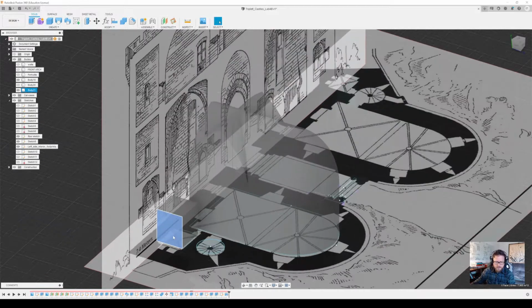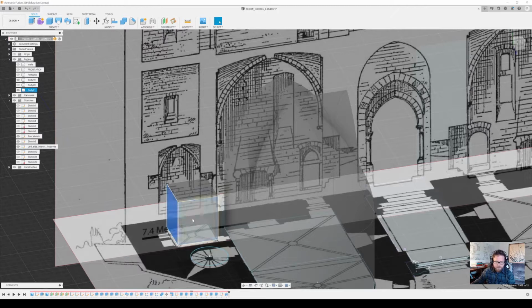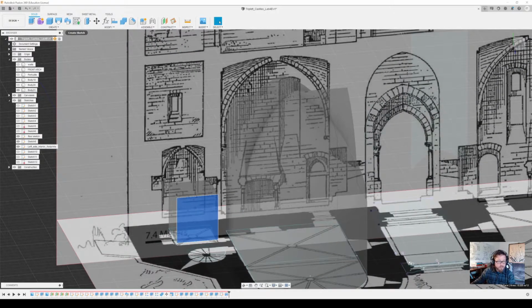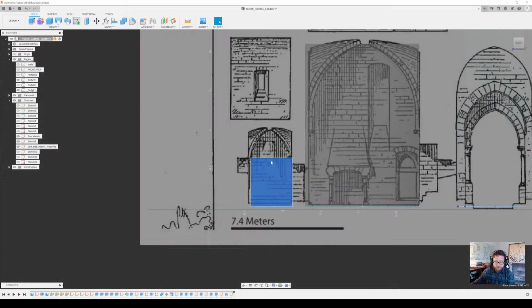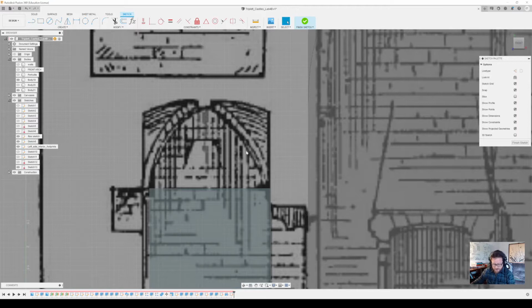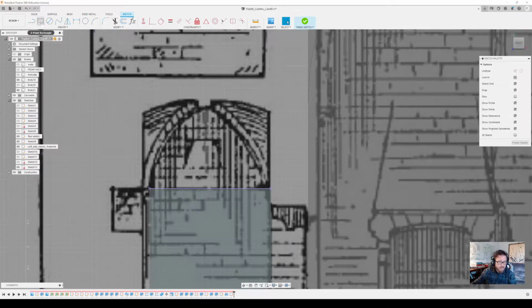So this little space, we're going to do that domical vault. That's going to take us in a little bit more complicated direction. Let's select this front one. I'm going to hit Create Sketch. Okay, and right in here, just as we've done in the past, I'm going to hit the P key, select this top line, and hit OK. The purpose for that, we've done a million times, is to get our center point, our center axis, I should say. I'm going to hit X.